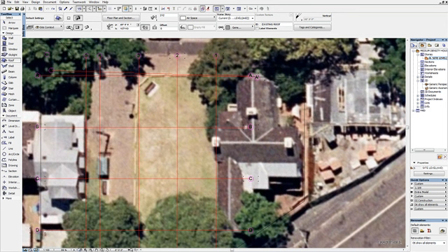For example, when we're looking at a roof, in the information box we can nominate that the roof is going to be a single roof or a polyline roof, or for a wall, a single wall, a polyline wall, or a square wall, or a wall that is square but on an incline. Notice that the information box is the geometry mode, the drawing method, or how we go about drawing in plan. The toolbox holds the parameters that mostly relate to the vertical information that ArchiCAD needs to know in order to draw this correctly or draft it correctly in both 2D and also now 3D.